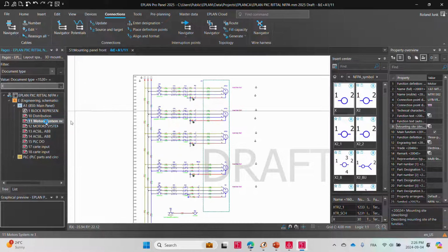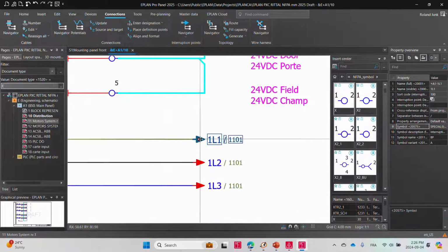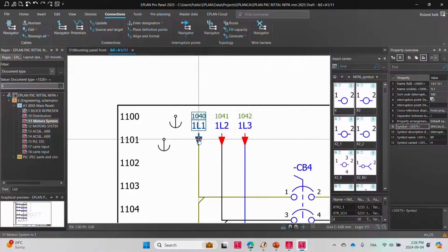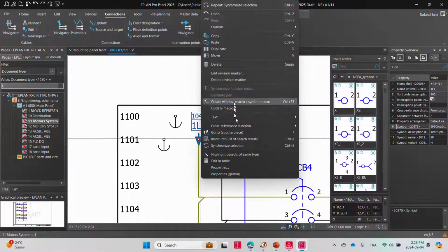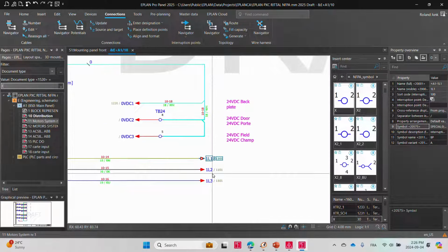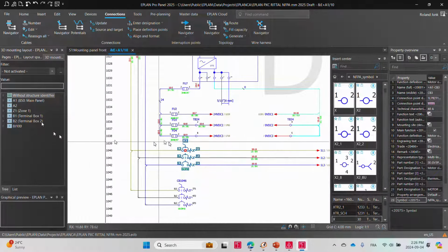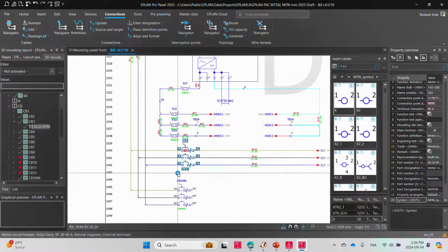Another thing that is interesting, and you saw this maybe earlier from some others, when you want to navigate to the cross-reference that is there, just hit the control button, put your finger on the green text, which is the cross-reference, and it will simply bring you bingo to the cross-referenced element. I was using earlier the go-to counterpiece. Works kind of the same way because it's a unique counterpiece. There are different ways to do that. And there's also another interesting trick you should know: if you ever have a component that you want to find within the navigator, right mouse click, synchronize selection.